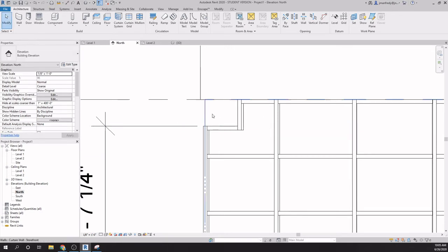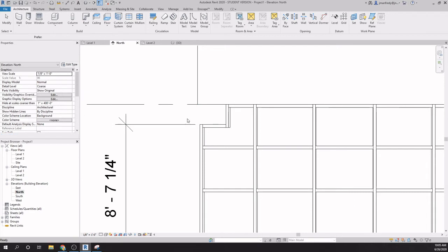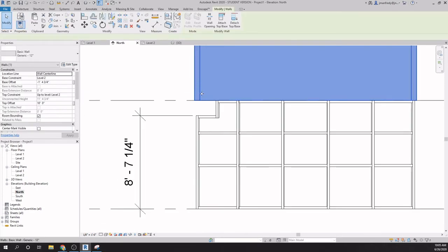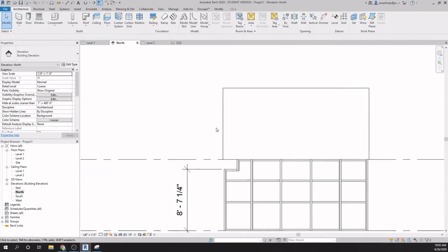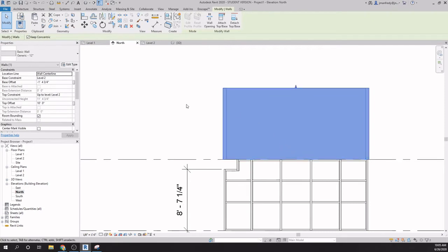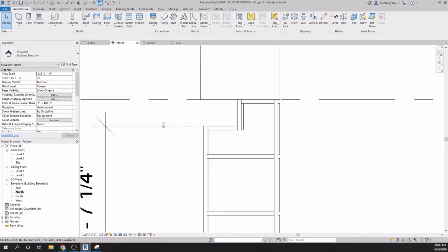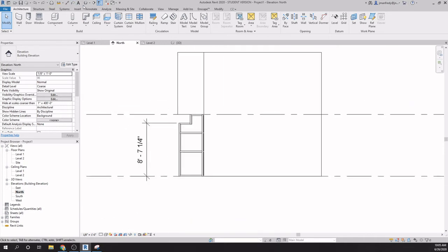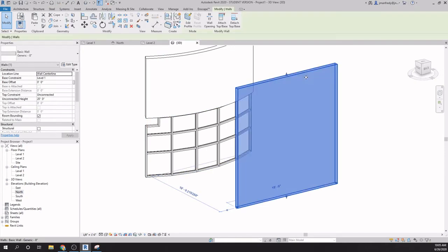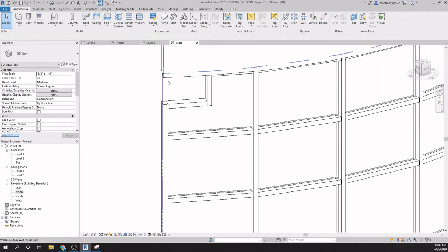and something may have appeared. Okay, so AL for align, go to here, choose the bottom of this wall, and it's not doing anything. Let's pull this down further to exaggerate the fact that it's going to be pulled further down. It might have grabbed something by mistake, so I'm going to undo this for a second. Control Z, Control Z. Let's see what's going on. Oh, there's my sample wall. Delete that. Let's try that again.